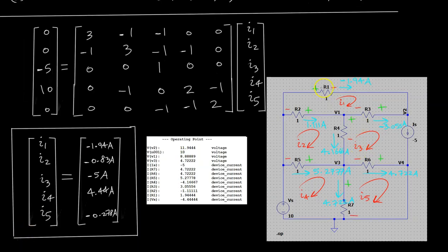Okay, so I've also added the assumed polarities for the resistors. The mesh currents as well as the resistor polarities are what we assumed from the get-go. Looking at these, we can see that the current 1.11 amps through R2 is going opposite the passive sign convention, and so we would expect a negative sign there.